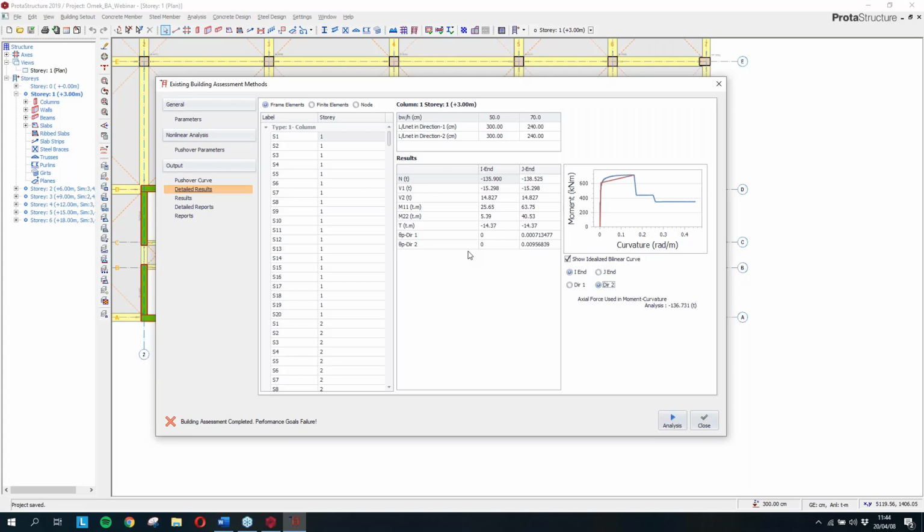For shear walls, we are also using 6 integration points, and we do not concentrate on one region. We just simply give a nonlinear definition to the whole member, to all integration points.